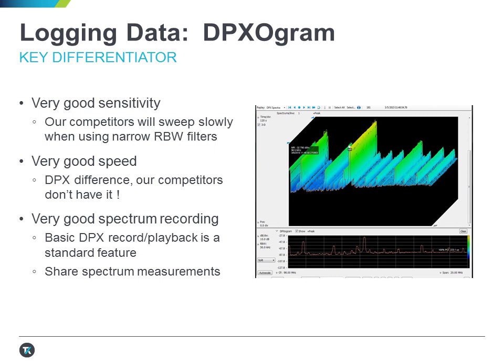That's where DPXograms or spectrograms come into play. They show us power spectral density over time. In this case, real-time power spectral density over time. With this display, we can see how often a signal is happening and actually do a carrier correlation to determine how an intermod is actually occurring, or when the intermod is actually occurring.